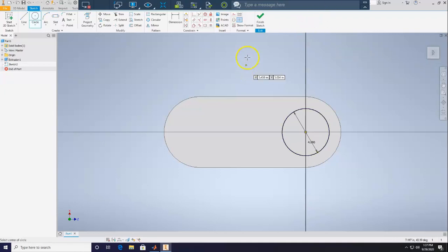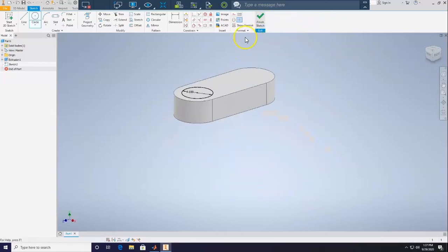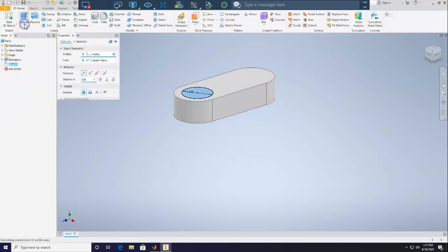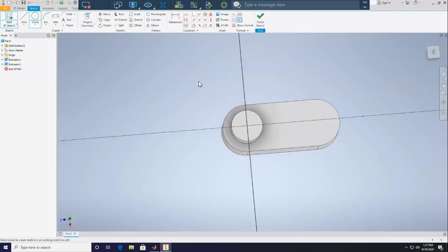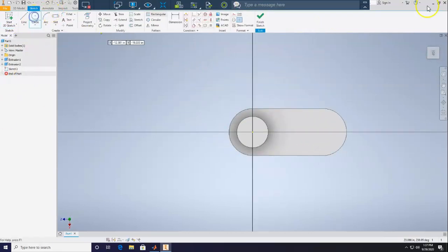And that's actually it for this sketch. Now I can extrude this, and if I extrude it in the other direction, it could have been the hole on the one side. If I went this way and went all the way through, that's the hole on the one side. If I add material and go up 2, on the other side, we are working towards building that tiered section. So now I can do another 2D sketch. This time I'm going to draw it right on top of the other one, and I'm going to keep building up from where I was before.